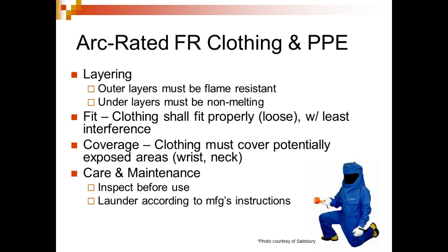Mr. Tate, we had a motor spinning in there, and Mr. Tate had his tie on. He leaned over that motor, and guess what happened? His tie got caught in the shaft of the motor. And luckily, Mr. Tate had his hands like this, and he locked his elbows, and it tore that tie off his neck, which is funny. We laughed about it, but it could have been really bad because it could have hung him, right? So loose fitting clothes around moving machinery is not good.